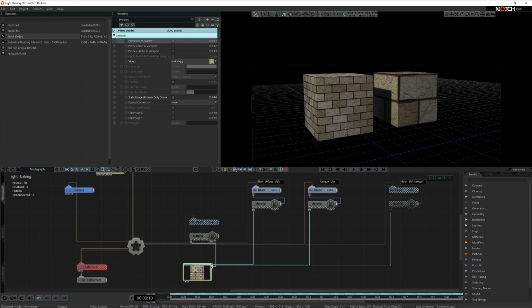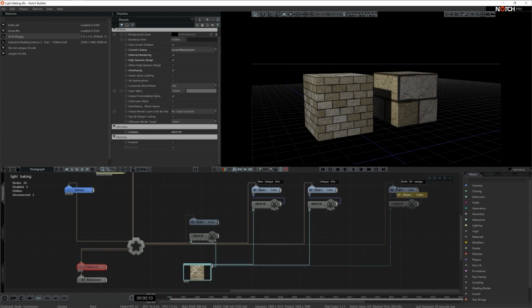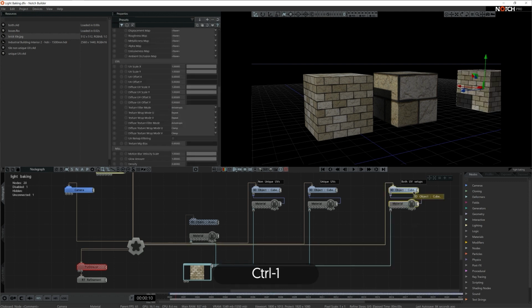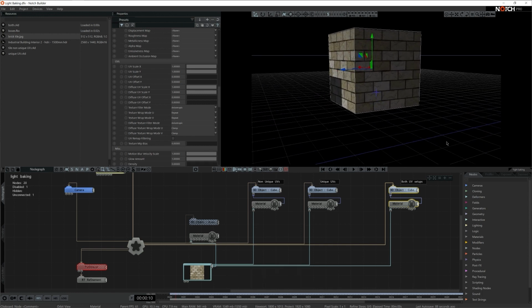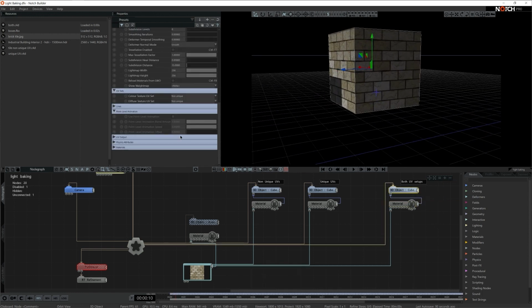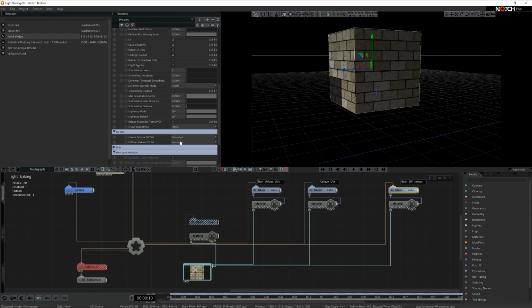So now we know the main differences between the non-unique UVs and unique UVs. Now, bearing in mind that there is good reason to use both of these techniques in your projects, I will mention that you have an option to use one and the other on the very same 3D model because you can assign multiple UV maps. So here I have a third cube, which is also exported from Cinema 4D. It's just that in this case, instead of having one UV pass, it actually has two.